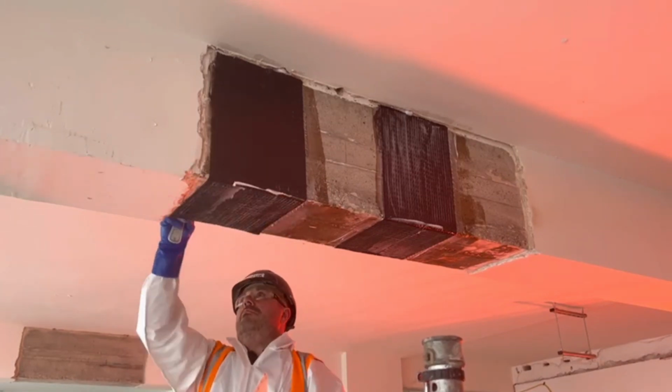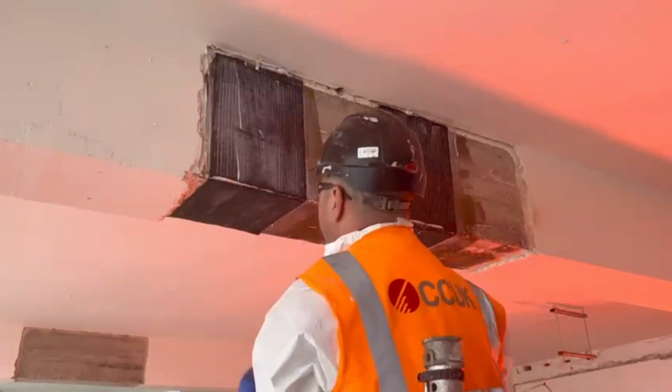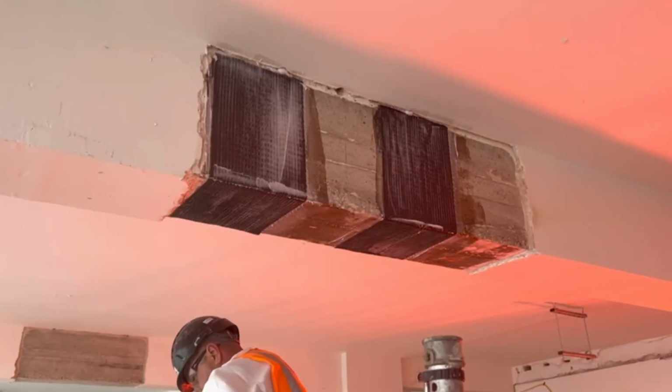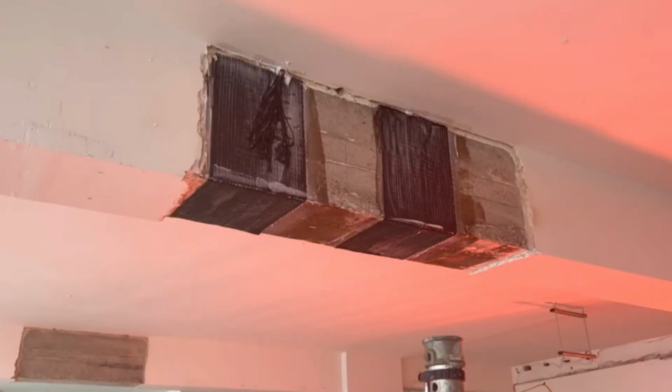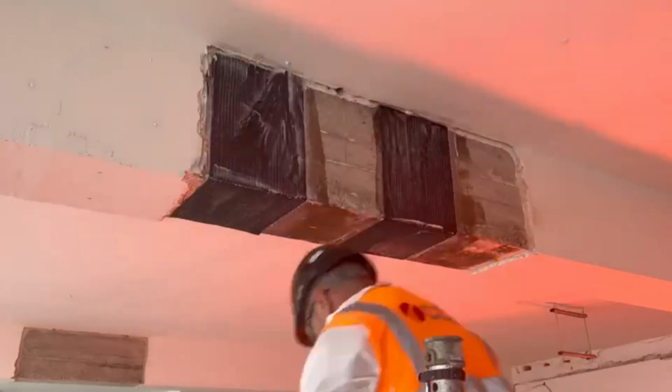So once that is done, the final layer is applied, then they apply a final coat of epoxy and finish the application that way. After the application, if there is a requirement to apply additional coatings such as a fire protection coating or paint coating or something, you can apply that. But to be honest, FRP is good with anything. You can plaster it, paint it, render it, you can do anything on top of it.